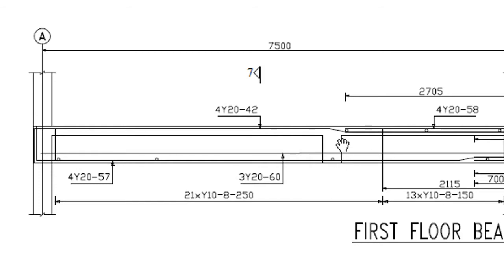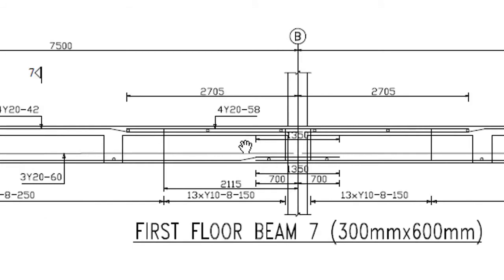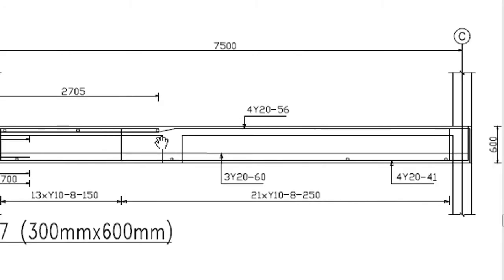So if you continue tracing that line, see there, you can see it's telling you that there is another section of a beam here. You can see there's another section of a beam here too. So you keep tracing again, you see it's telling you that there's another section of beam here. Keep tracing, then it comes down to this place, which is an external line. Again, it tells you that there's a column here. You understand? So this particular line is not a reinforcement.